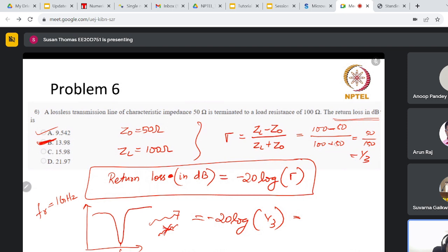With reflections as minimum as possible. That is why we do the impedance matching. For that, the reflections should be minimum. That means in the return loss we have to have a larger dip, so the antenna is efficient and has a minimum reflection at that particular frequency. If people have worked on antennas and such areas, you would have already come across this particular term, return loss.